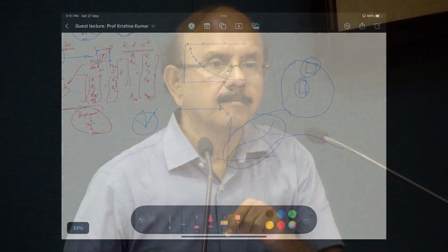Take a small piece. For example, our friend here is doing a tire, so take a small piece of rubber and find out the stress strain curve. Then you will get a stress strain curve like this. Then you have, as madam asked, a hyperelastic model. Your model has 3 quantities, C10, C20, C30. Fit the strain energy function for this curve and then feed C10, C20, and C30 into the software. Material for a tire is okay, sir.